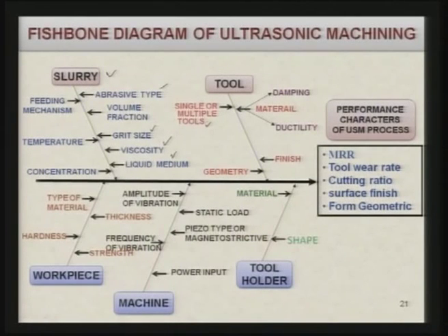Now, the material of the tool: what are the damping characteristics of the material of the tool, and what is its ductility? This will also affect the performance of the ultrasonic machining. Another very important factor is the finishing of the tool, because, as I mentioned some time back, if scratches are there or micro cracks are left, it will quickly fail because of ultrasonic vibration and the load acting over it.